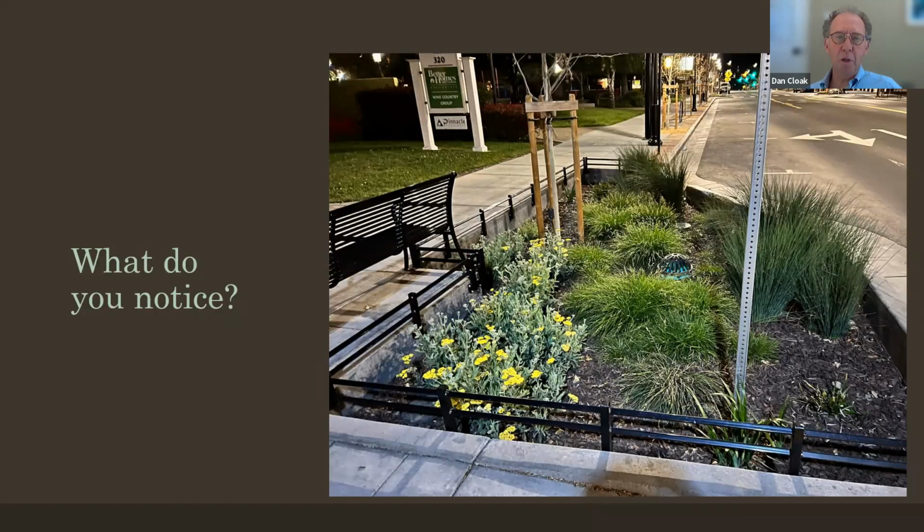Does the tree need soil rather than BSM, bioretention soil media? And the answer is, in my experience, typically not. There's a group in the MRP counties that's just gone around for years and years about the problems of trees and bioretention soil. And I participated in some of the discussions, and I was like, well, but we've got 20 years of experience now, and we've got great big trees that are sitting in bioretention facilities. Let's go figure out what was done right, why those work.